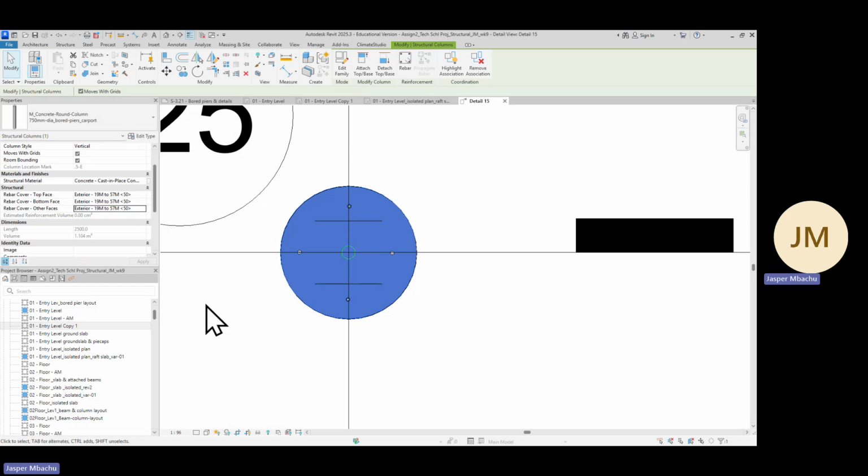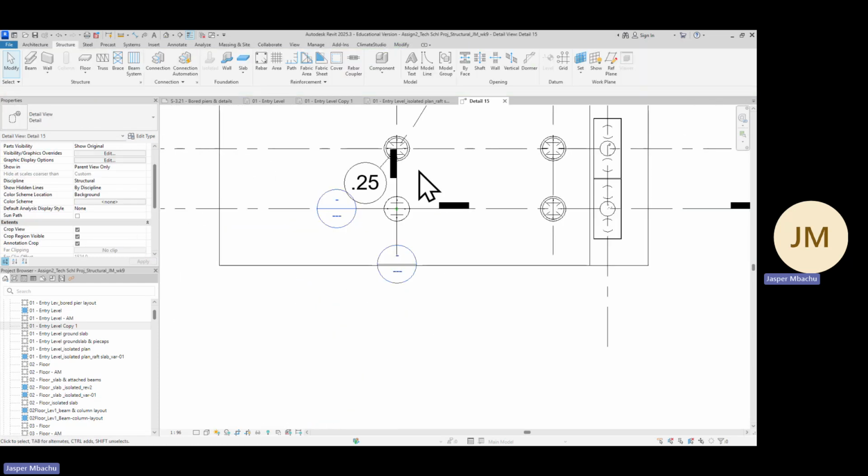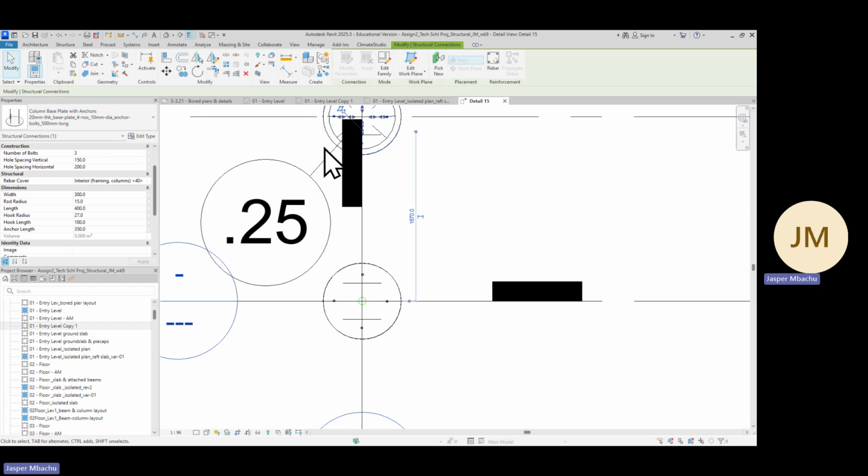Unfortunately, they couldn't do it for all of them. I wanted to do it at once. And then when we come back, we'll continue with the rest. So you select the column again. When you select it and it's showing column, not anything else, it will show you the cover too. And you select 50-50 cover for all those 7 columns.